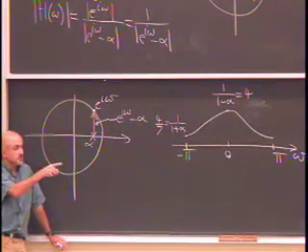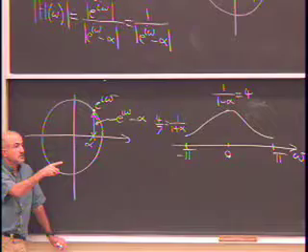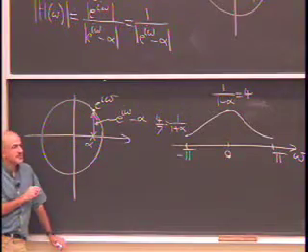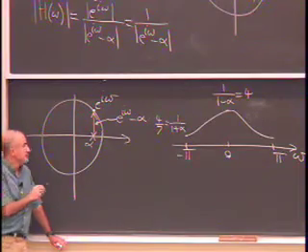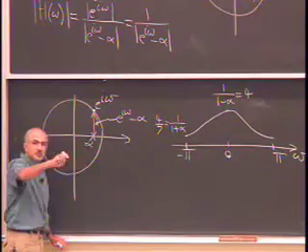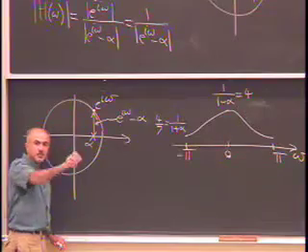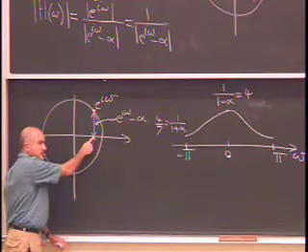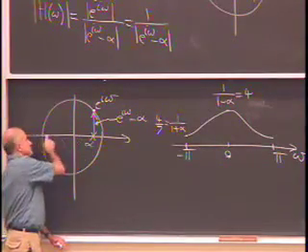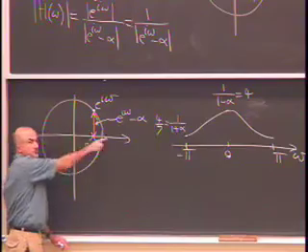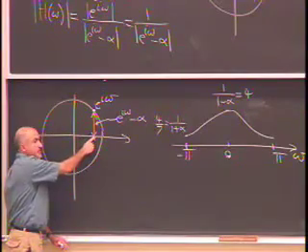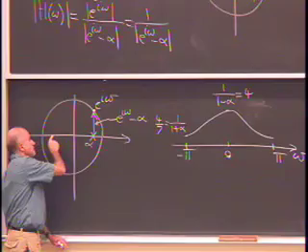Well, my answer would be to use a negative value for alpha. So all you have to do is, if you have a design parameter or a knob on your box, and you can turn that knob so this alpha moves between -1 and 1, to make this high pass, all you have to do is take this alpha to the other side.